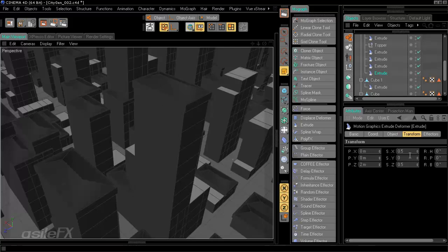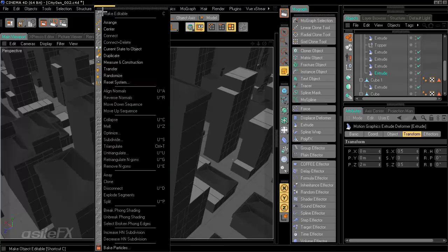The polygon does still exist. So if you were to bake this object, which all the clones can be baked, provided they're not rendering instances, the individual objects are created. Even if you were rendering instances, the original object that was created with that kind of rooftop, you could just optimize under functions, select optimize in order to merge the points and get rid of that top polygon.